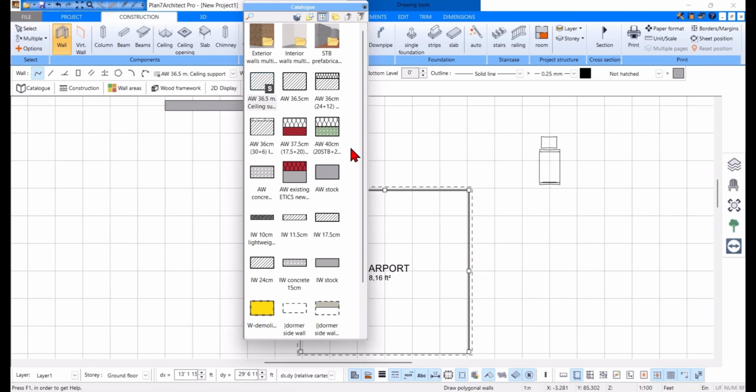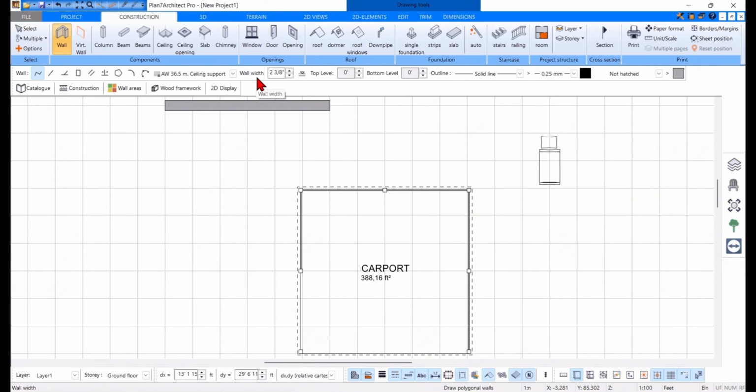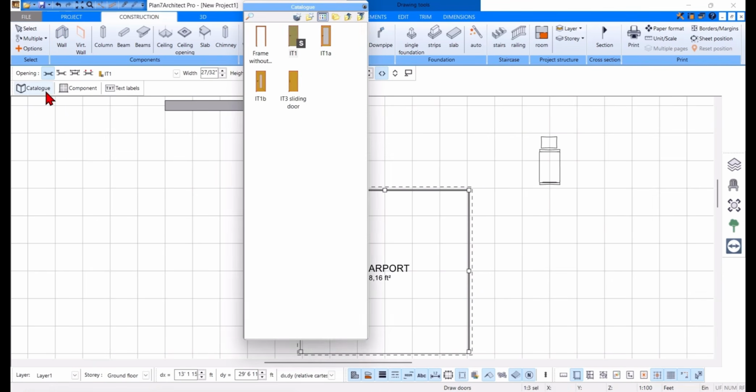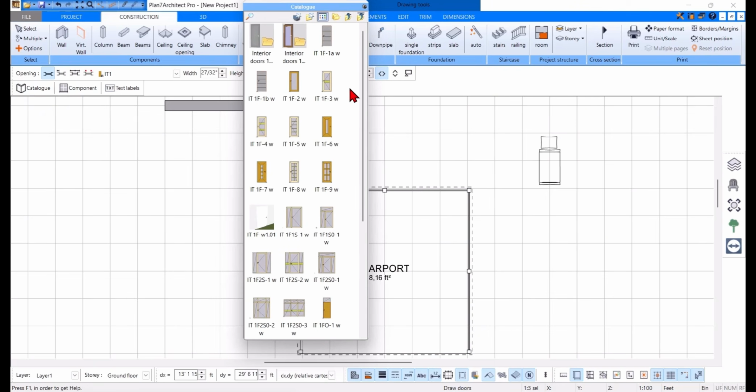In the catalog, the walls, doors, and windows are all stored in meters. This might appear confusing, but it's not an issue, because when you're drawing, you can immediately input the correct thickness and length in your chosen unit. You can input these specific values right here. This catalog functions just like the other catalogs that we have already seen. If you only see a limited number of doors within the Door function, please click on Folder Above in the catalog to display the other folders or available options.